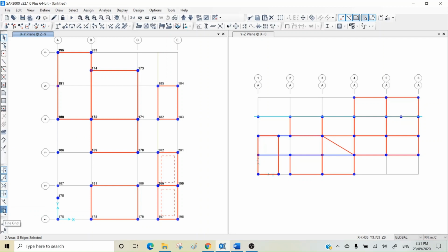So fine grid is when you are here. You will set it up in the tools that I show you later, but this fine grid is coming, and if you have a look at this area that shows you the coordinates of the joint, when I move, for example, it is currently set based on 250 millimeter or 0.25 meter. So if I move very slowly, you can see it just going in steps of 0.25.